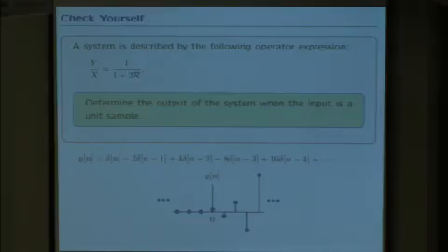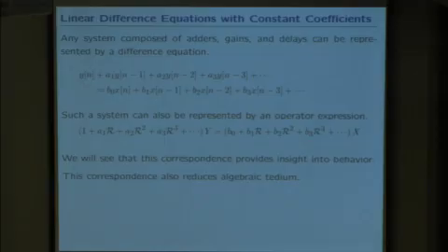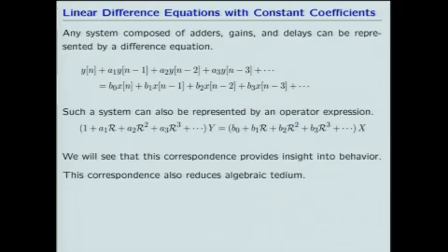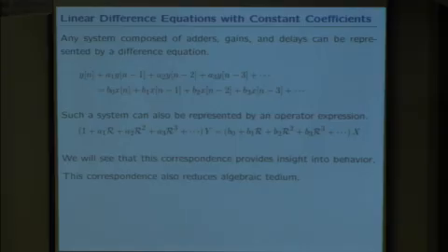That's the point. In fact, the point of today is that any system that's built out of simple parts, delays, adders, scalars, that sort of thing, can be represented by a difference equation. Fine, that's good. Difference equations are wonderful. They can equivalently be represented by an operator equation. The operator equation has more information in it.